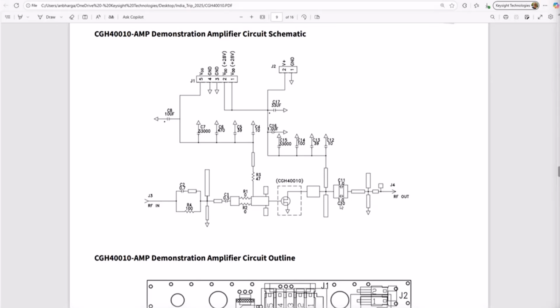So the link which I shared in the earlier slide about RF design tutorial, go and watch. There is an RF switch design example. That's a real case study done with a customer. And you will understand what are the implications of mounting these components in parallel. So in your circuit design, you may be simulating it as maybe 2 picofarad, but now you are connecting them in parallel. This performance may not be equal to 2 picofarad and so on. That's what I'm trying to say, right?